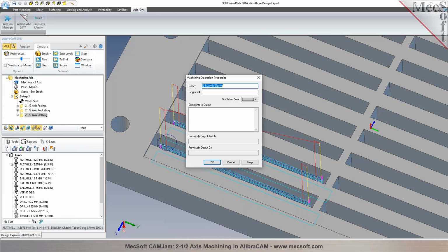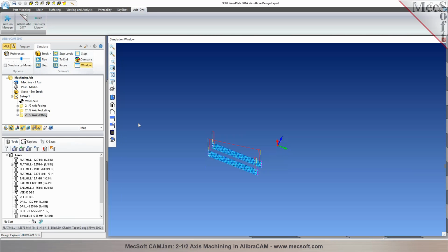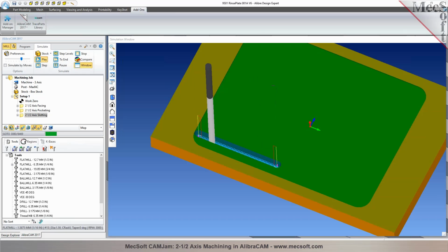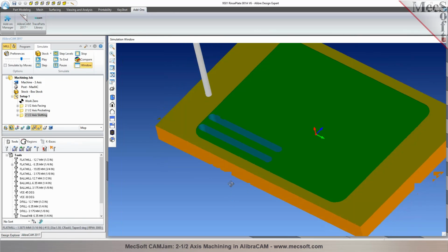Okay. So what's the downside of setting that to a very high accuracy? Well, it depends on what your machine can handle. If your machine is not capable of handling a tighter tolerance or number of decimal accuracy, the machine may not have enough look ahead, so you might see some kind of jerky motion on the machine since it's not able to handle that many close points. Okay.